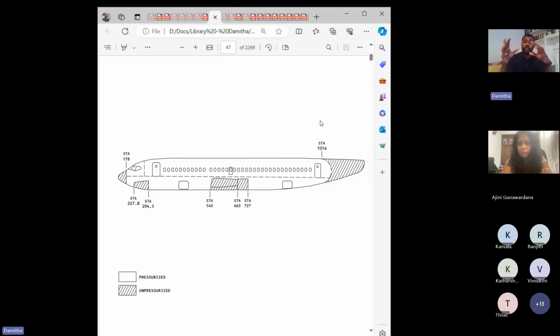So in the industry, there are pressurized aircraft and unpressurized aircraft. Unpressurized are these small little Cessnas, the single engine turboprop ones that you have seen. People can fly and land without too much hassle, and it's easy to maintain because it doesn't have that pressure difference problem. But the pressurized aircraft, mostly the long haul passenger ones and almost all commercial aircraft, need to maintain pressure within the cabin so that people don't suffocate.